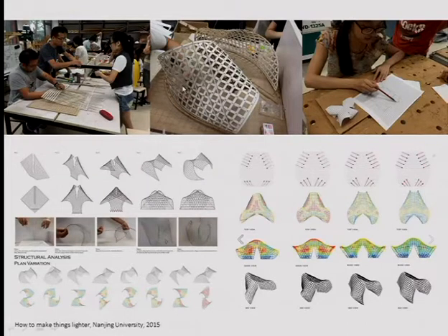For instance, this one was done at the same time by means of a physical model, paper first, and then they play with a steel mesh, and then they do it out of boxboard. Then they also do it digitally to make sure that the shape is completely controlled. They run a structural analysis, they go back to the physical model. So it's a back and forth. I don't want to say that now we need to use only numerical tools. Now we need to use both. And we need to use both and go back and forth and have a continuous feedback from physical and numerical tools.